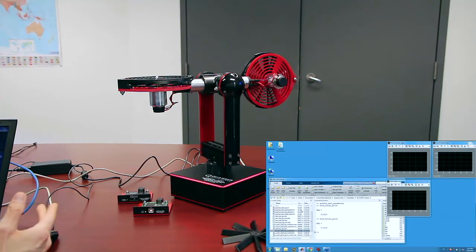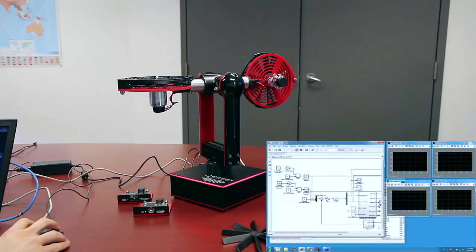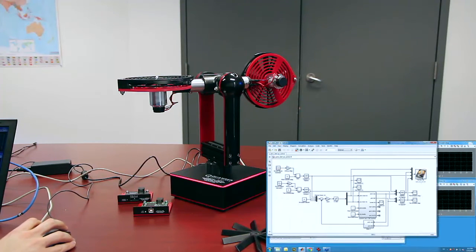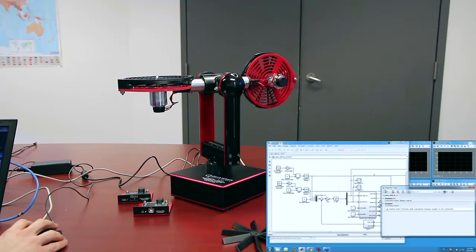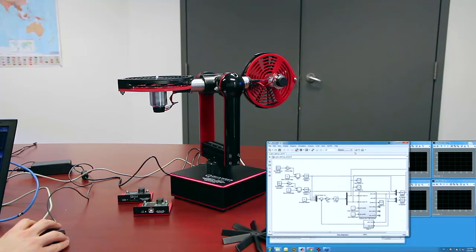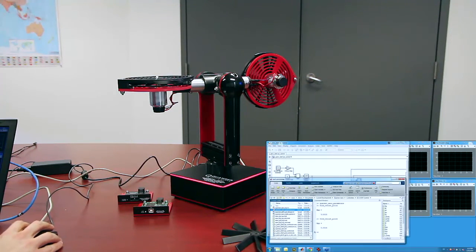So now let me show you a different approach. This is using a state feedback controller, which is a coupled design. So the model that was based on deriving the gain, which was using the linear quadratic regulator method, or LQR, was based on a model that does have this coupling effect. It takes that into account. So now if I run this using the same set point, so a pitch and yaw set point are the same, I'm just going to go ahead and build this.